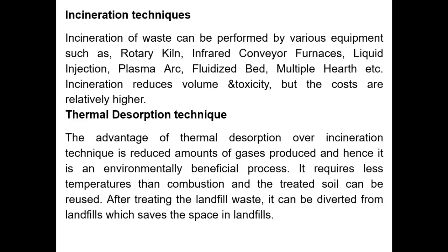The advantage of thermal desorption over incineration technique is reduced amounts of gases produced, and hence it is an environmentally beneficial process. It requires lower temperatures than combustion, and the treated soil can be reused. After treating the landfill waste, it can be diverted from landfills, which saves the space in landfills.